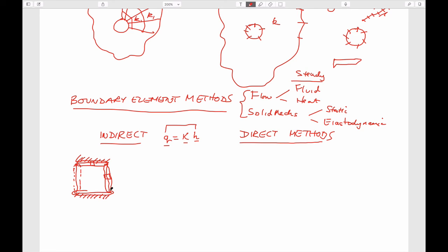And by a source for the flow problem, I just mean that it's sucking water into this little slit from both sides. Just imagine we could cut this and make a little slit and suck fluid from the porous medium that exists to infinity on every side, and we could figure out exactly what the impact of that removal of fluid was, say on the pressure or head at each of these other locations.